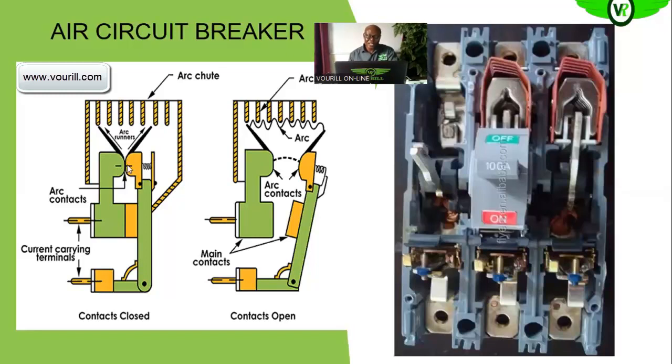The arcing contact, in larger circuit breakers, is made of materials that you could easily replace, okay? While the main contacts are made of more expensive materials, whose replacement can cause the replacement of the entire circuit breaker. So we need to protect it from destruction, okay?